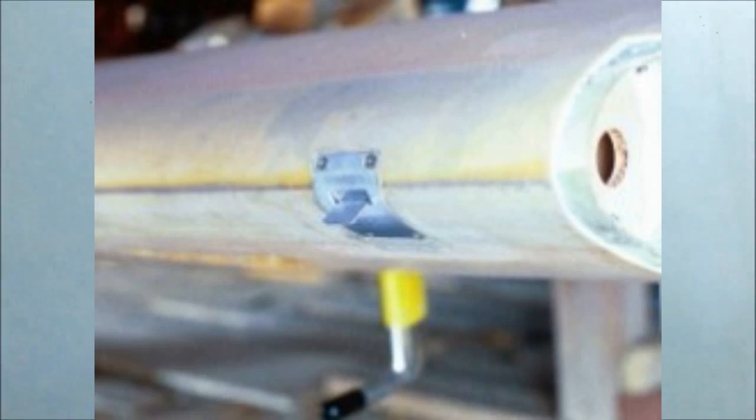Pneumatic system is common on light aircraft. This system consists of a plenum chamber and an adjustable plate. The plenum chamber is mounted in the wing leading edge. The adjustable plate can be adjusted so that in normal flight attitude, a slot in the plate coincides with the stagnation point of the wing, acting as part of the leading edge.